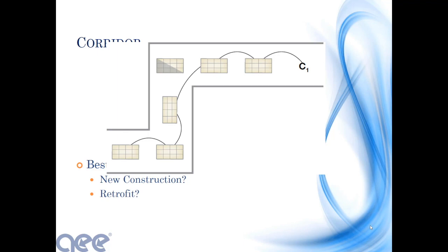Is the device that you pointed out wireless? It is, yes. And there are any number of manufacturers that would have a module that goes at the fixture that would then communicate wirelessly to occupancy sensors and daylight sensors, and then potentially either just be standalone like that, or go upstream into some type of hub or network that could go into a building management system as well. So you can get a wireless or a wired solution from multiple manufacturers for all of your fixtures, depending on what the control requirements are and what the sequence of operation is.